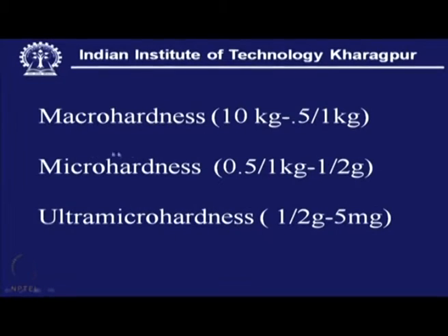So, this is number 1, and what is number 2? In a manufactured surface which is already machined, ground and already attained some finish, which is totally complete, the job is complete in every respect, and in that case if one would like to assess the hardness of the finished product, in that case also this micro hardness can find its use, because this is not going to make any dent on this surface, superficial or very visual.